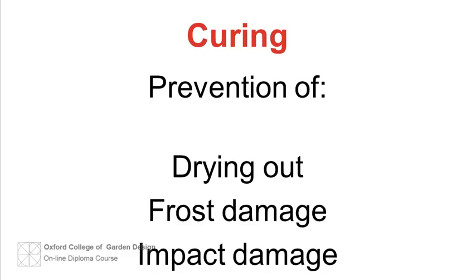Concrete itself generates heat as part of its setting process. So if the section of concrete has plenty of bulk and it is covered over soon after pouring, it should suffer no harm from a moderate overnight frost. Proprietary spray-applied curing compounds will seal the surface against hot or windy weather, preventing rapid drying out. But covering in polythene membrane is more effective and visible in both hot and cold weather.